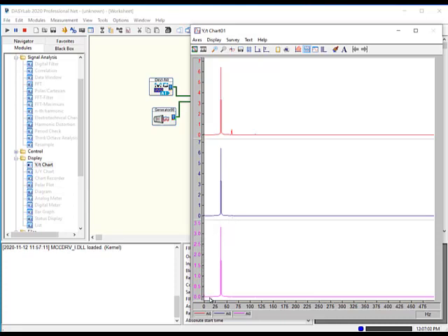The average module, averaging over 16 samples, is removing almost all the energy as well, but it also damped the peak. So the peak is running about 6.5. It stayed about 6.5 for the filter data, but then it's down to a little over 3. So it's diminished by at least half when you average over it.